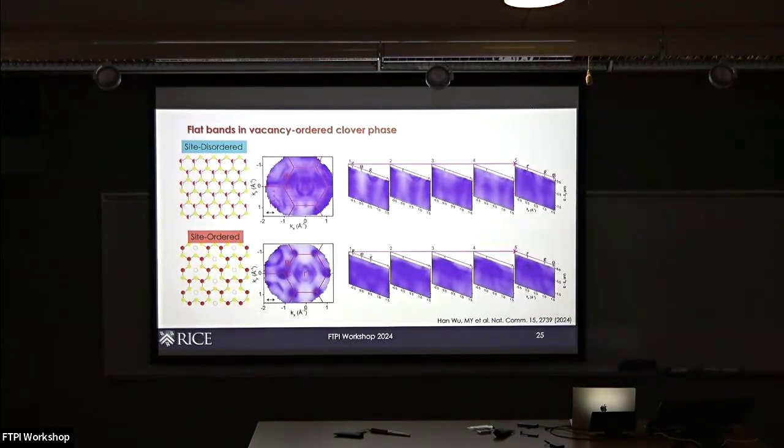But in this process, from XRD, we always see the superlattice peak due to this vacancy order. Basically the way to switch is by quenching versus slow cooling. In the quenched samples, you have much brighter superlattice peaks. We have also done STM with Eduardo da Silva Neto's group. They only see ordered regions in their field of view for the quenched samples. And this one is largely disordered with small puddles of ordered regions. So we have never gotten 100% volume fraction for one or the other, but we can see the volume fraction depends on this treatment method.